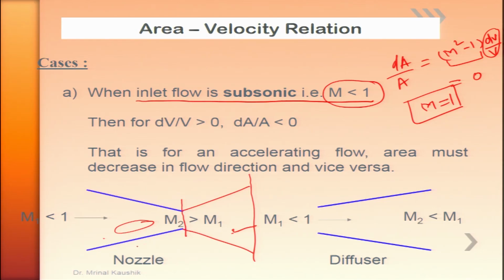Here we should understand this point as well: since we are considering the straight boundary, which you can observe in the schematic, a straight convergent divergent boundary, when the flow enters like this and is assumed to be attached to the internal boundary of the divergent section and not separating, will give you the flow at the exit in different directions.